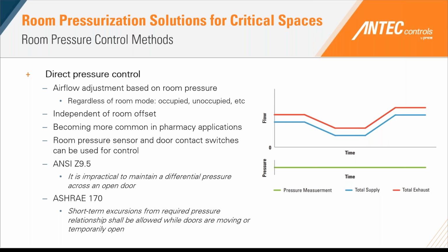To enable this strategy, you will need a room pressure sensor to take live readings of your pressurization, and door contact switches to monitor when the door is open. ANSI Z9.5 states that it is impractical to maintain your differential pressure across an open door, since in most HVAC applications you're not designing your room pressurization for the door being open.